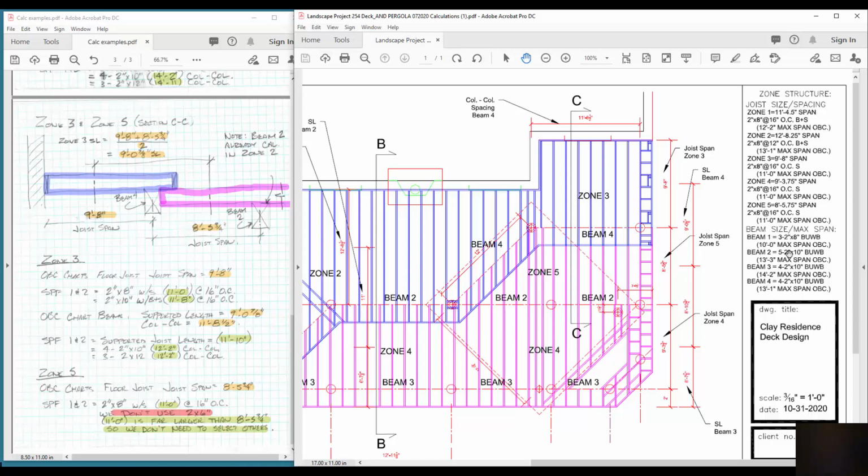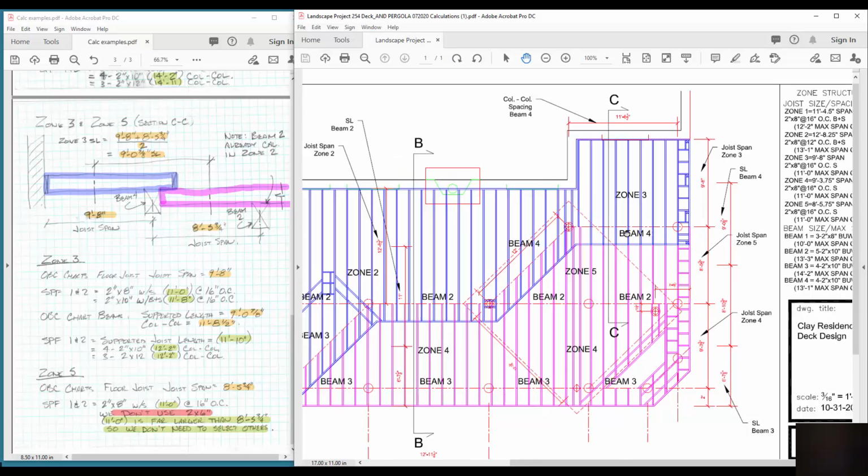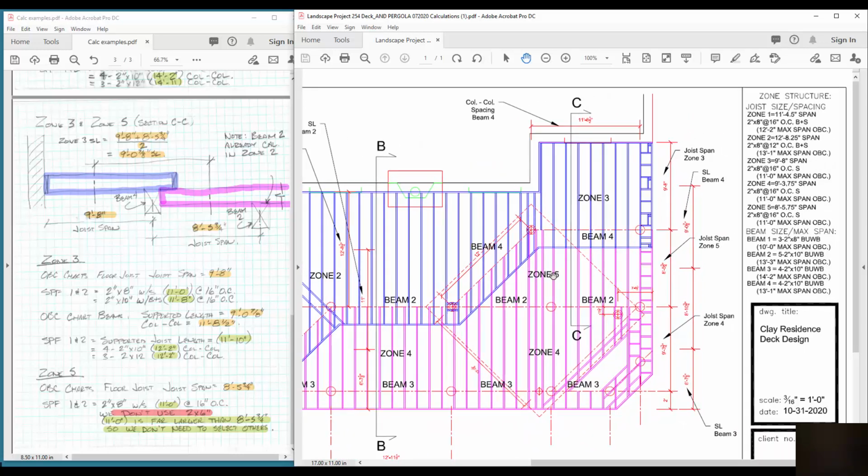And then I've got all my max spans on each one of these right on the drawing. So in case somebody is building this off the drawing and they're digging holes, and for whatever reason they can't place the column in that hole, there may be a lot of rot, there may be sand, there may be moisture, whatever the reason is, and they have to move the column, they can immediately look at this chart and say, oh, how far can that span be on that column? Okay, we're still safe within that distance. It just helps the builder and saves some time without them having to come back and forth and identify some sort of amendment to the drawings, or they know they can go ahead.